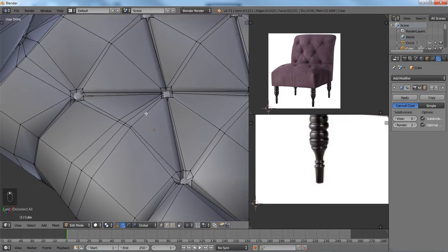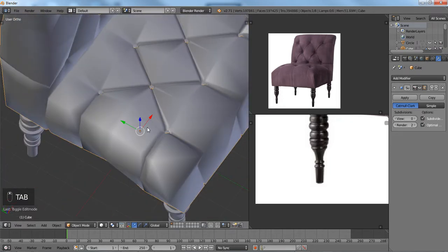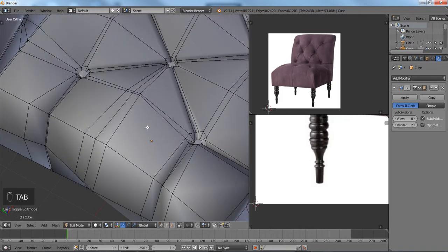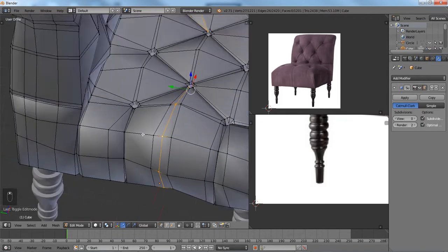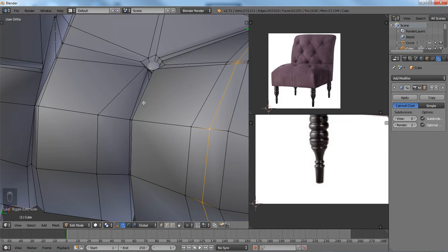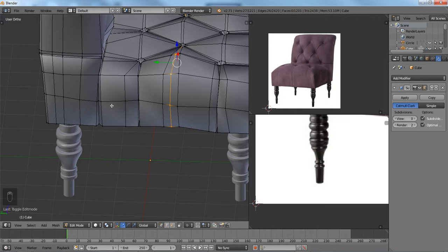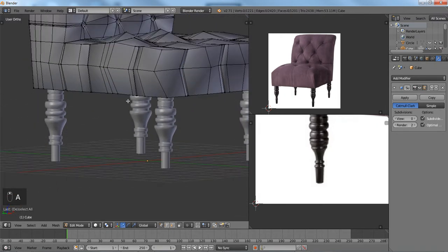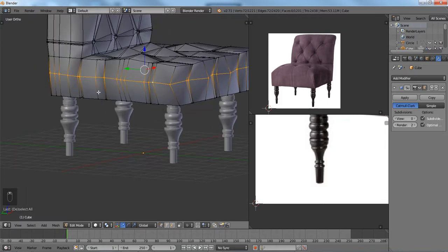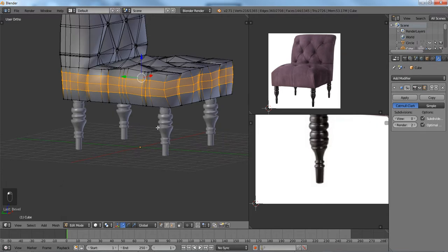And pretty much with these creases over here, if that's even considered a crease. Oh yeah, I didn't even do that one, I think. This is just added detail, just add extra edges. But for these creases, just bevel and just scale them in, and then I would use my sculpt brush, my inflate brush, and then just pinch it a bit more precise together. And if I can select this whole loop, I'm going to bevel it. And also, when I finish adjusting this, I'm going to explain a little bit on what I did with the legs.